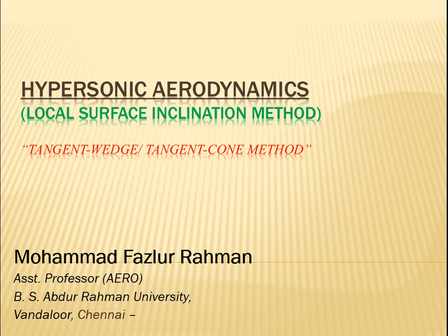the experimental results and the exact results as well. The reasons are different for different methods, and we have already seen one such method, something called Newtonian flow theory, Newtonian flow methods, or Newtonian sine squared law, in which we know why it is very much close to the hypersonic flow regime and giving the ideas about the correct values, but it doesn't make much sense. Still it is matching. Now we are going to study a different method today, that is tangent wedge and tangent